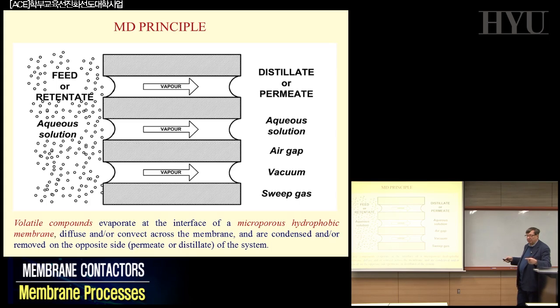The way to measure the hydrophobicity of a polymeric system is to measure the contact angle on the surface. If you drop water on your skin, you form a droplet. You can measure the contact angle, and that gives you an idea of how strong the hydrophobic character is. Assuming this is strongly hydrophobic, no liquid can penetrate; it would be rejected.